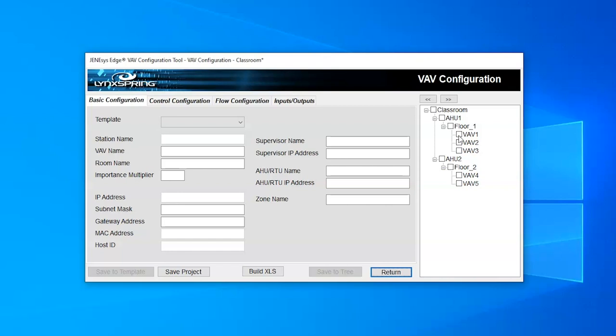And I take that among anything, regardless of whether it's doing something like this, or if I'm in an Edge controller or a Jace. I like to have multiple saves for my station to make sure that in case of a power reboot or a power loss, I don't lose as much information as I need.